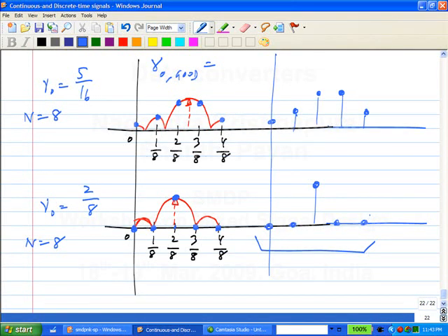Because this spacing is 1 by n. And this spacing is also 1 by n. Between the peak and the null of the sinc, it is 1 by n. You think of this as a coincidence. Because you truncated it to n points, you will get some sinc-like shape, and there are nulls in that sinc, and the nulls are separated by 1 by n.